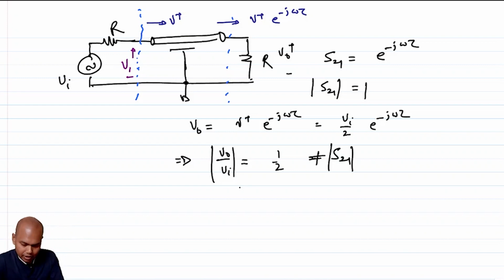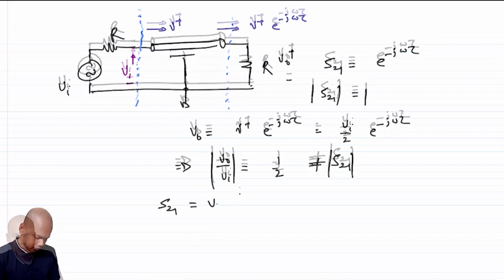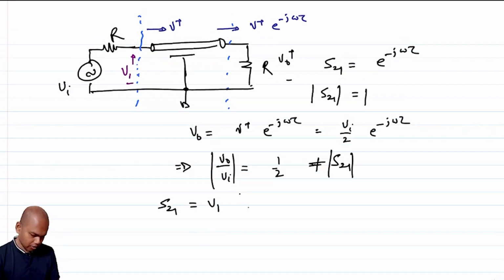Now, if you recall, we had talked about this briefly in probably the last lecture, that you have to be careful about voltage gain and S parameters if your interfaces are not matched, because by definition S21 is valid under matched condition only, when all ports are matched.